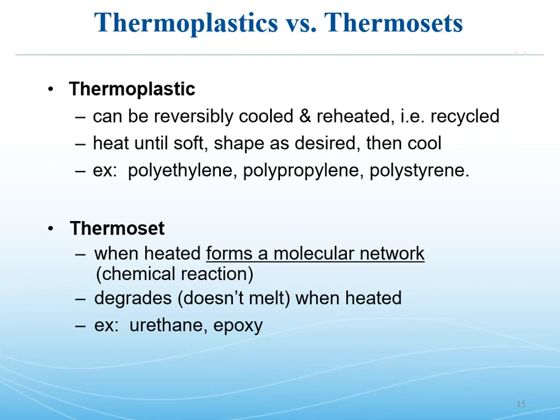You can have some secondary bond interactions in the case of thermoplastics, which we saw in the case of nylon, where you had that positive charge on the amine group being attracted to the partial negative charge on the carbonyl. Thermosets go one step further with full-on covalent bonds between chains. So the obvious big negative implication for that is you can't melt them and you can't soften them significantly. So they're very difficult to recycle, if not impossible. So you're stuck basically burning them in a cogen plant.